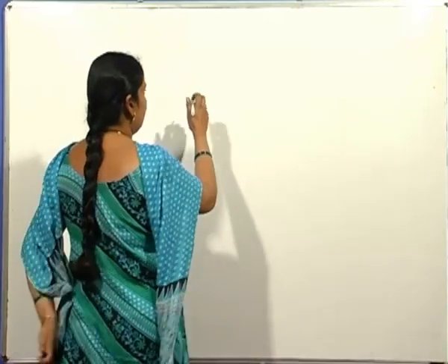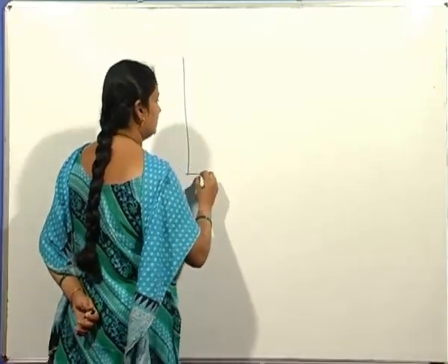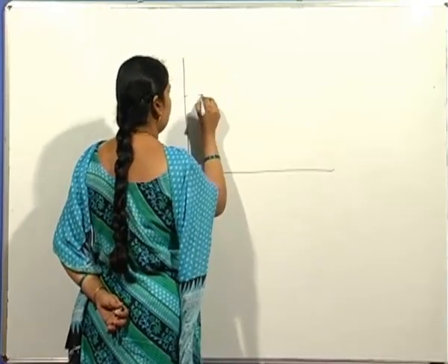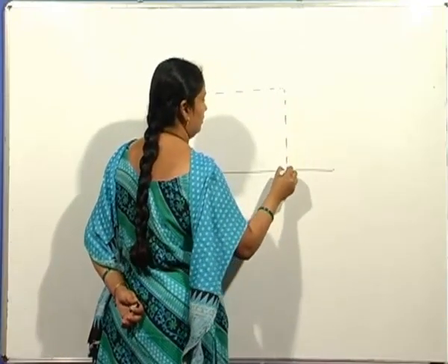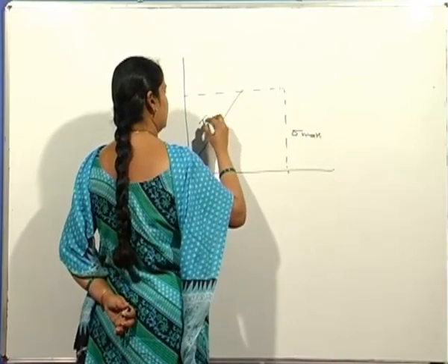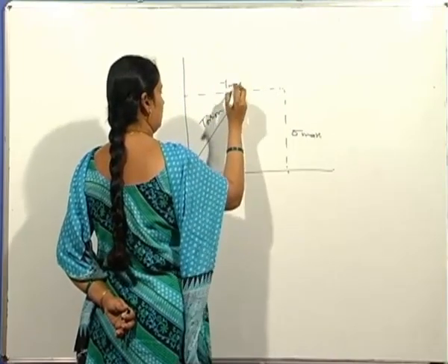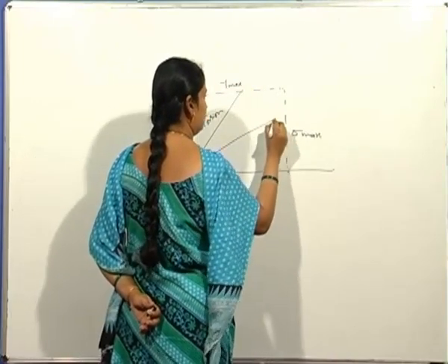In the case of torsion, large plastic strains can be obtained without the problems like that of necking in the case of tension and barreling in the case of compression. And this torsion test can be conducted at high strain rates. So for a case of material, tool steel, when it is subjected to both tension and torsion, this is for the case of torsion, this is for the case of tension.